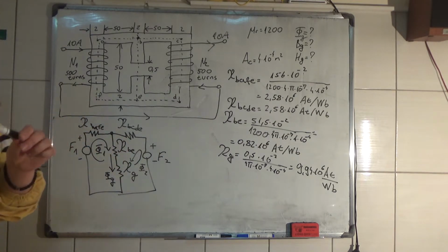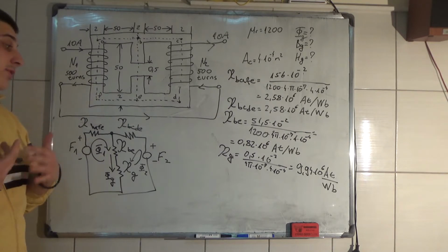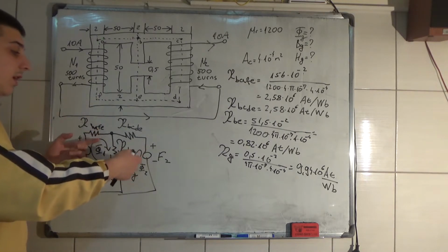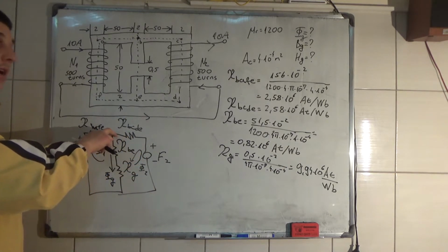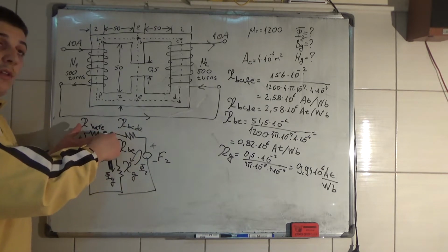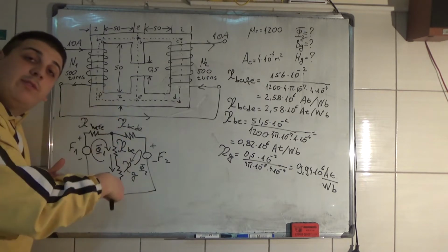It is equal to the sum of these fluxes that go into the node. So that's the analogy to Kirchhoff's current law, as in electric circuits, which states that the amount of magnetic flux that comes into the node has to be the same as the amount of flux that comes out of the node.